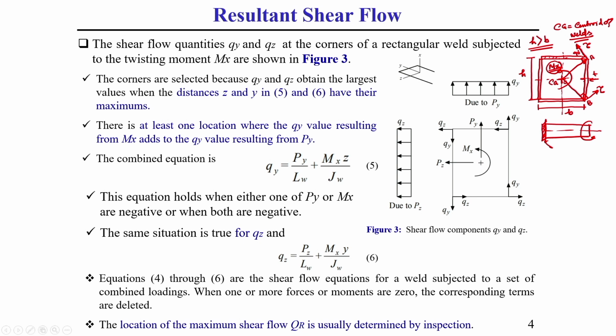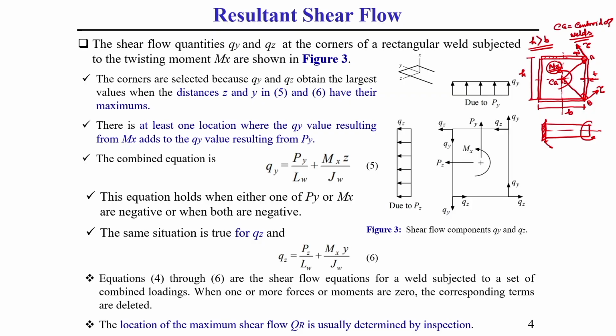So, always you should keep it in mind, we should choose that location where our shear stress is maximum. You should keep it in mind. The resultant shear stress due to, let us see what happens: a welded section, this weld, which is subjected to torque as well as it is subjected to two forces; here I have shown Py and Pz.